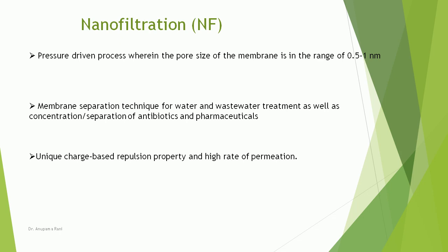NF membranes allow partial permeation of monovalent salts such as sodium chloride while rejecting bivalent salts and hardness to a greater extent from aqueous solutions. NF can lower TDS and hardness, reduce color and odor, and remove heavy metal ions from groundwater.